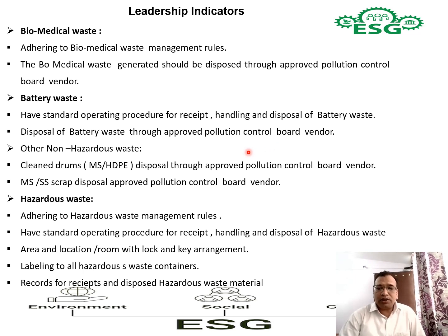There is another methodology that is called buyback. Buyback also has to be done through a pollution control board approved vendor or CPCB vendor. So adhere to those rules and regulations. Other non-hazardous waste, like we have spoken of initially, clean drums like MS drums, HDPE drums, carboys, glass, and paper, should also be disposed of through an approved pollution control board vendor only, and not to any other vendors, and it should be accounted for. Then MS and SS scrap disposal also has to be through the approved pollution control board vendor.